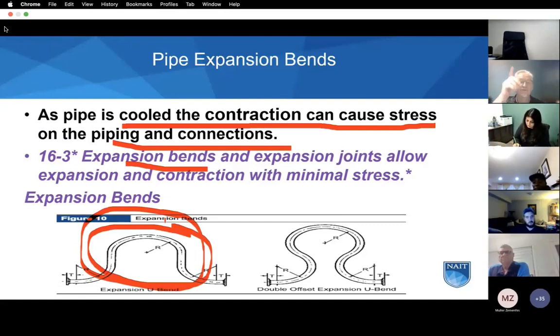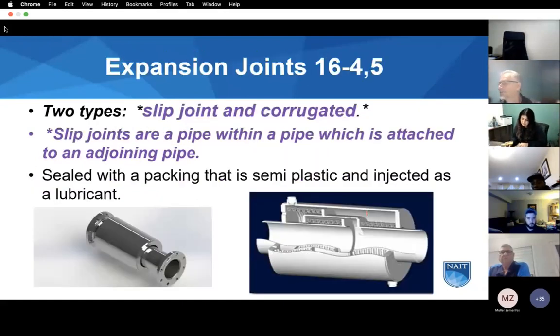And piping came from the utilities plant all the way out there, 4 or 5 miles, I'm sure, at least 4 or 5 kilometers. So there were lots of these bends where the piping went along the road for a while, then across the road in a loop and back across, to ensure minimal stress.